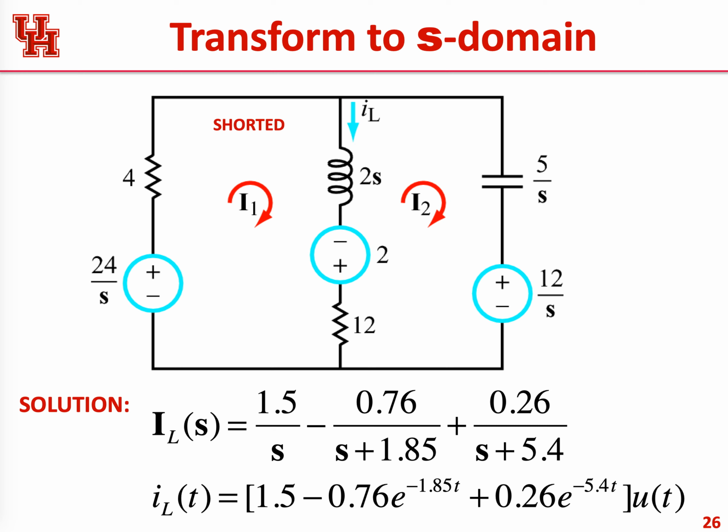But in series with that, we had to stick a voltage source, which is kind of pointed backwards. Remember, it's an inductor, so it's pointed backwards, okay? And this is going to be equal to IL times 2, right? 2 is the inductance, 2 Henry, and the initial current was 1, so this is going to be 2 volts, right? So like that.